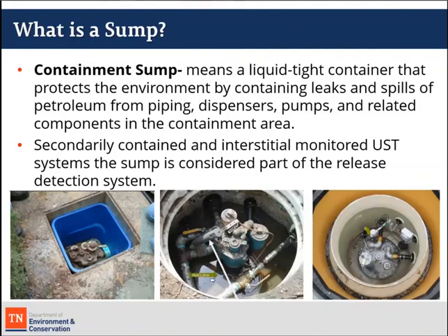This is a design sump, but as you can see, there's water intrusion coming into that sump. So it's not truly serving its purpose as a portion of the release detection system, either containing any petroleum that could be released, or keeping the water out of that sump.